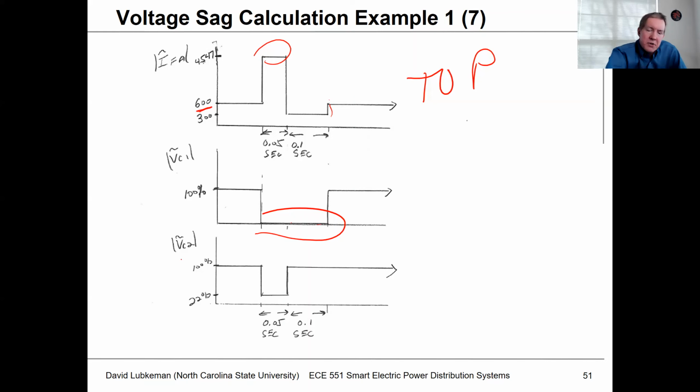On customer 2 location, it sees the voltage sag down to 22% for the time of the fault, which is 3 cycles. It's a pretty severe sag, so I don't know what's going to happen in this case for the loads. It's not a very long duration, so maybe those loads can ride through, but it's a pretty severe event because that fault was so close to the substation.